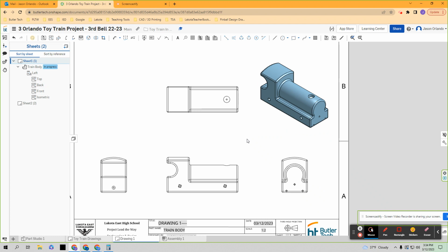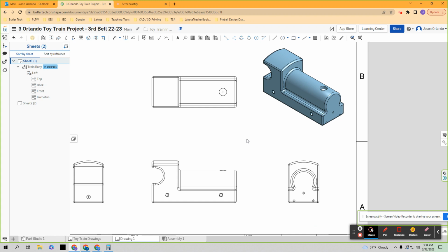Okay, now for dimensioning this, we need to keep in mind that our goal is not to put a length or dimension on every last little point that you can think of or distance, but it's to give enough dimensions that we actually understand the size and shape of the object, and we have located things. So we do not need to locate something 2 times, 3 times, 4 times. And the mistake often is that students start over dimensioning because they don't really think about, did I locate something? Did I help know where that is? They just kind of start blindly putting dimensions on things. Okay. So keep that in mind.